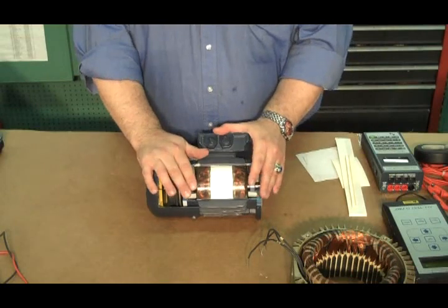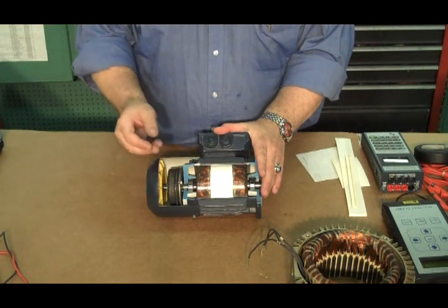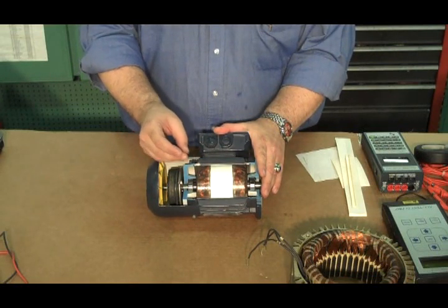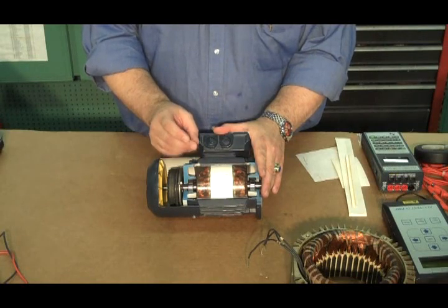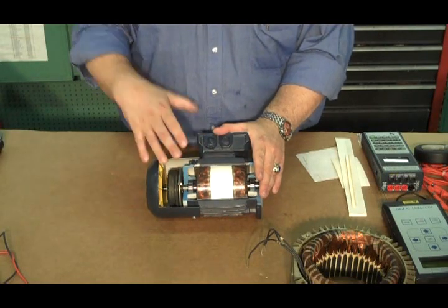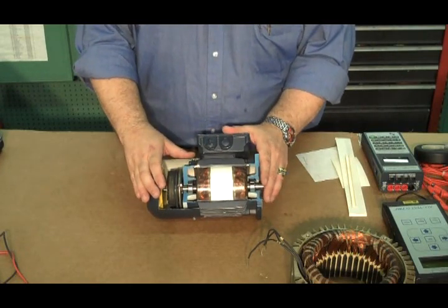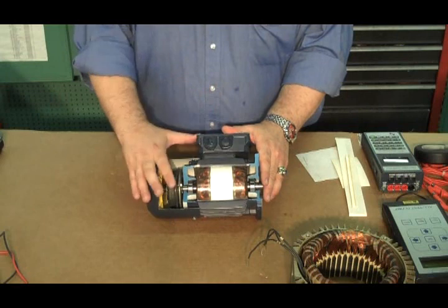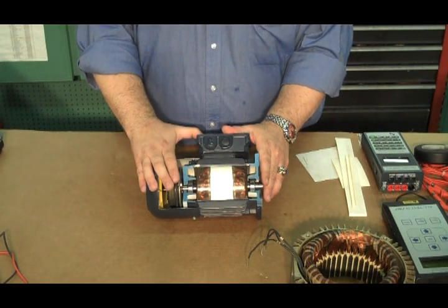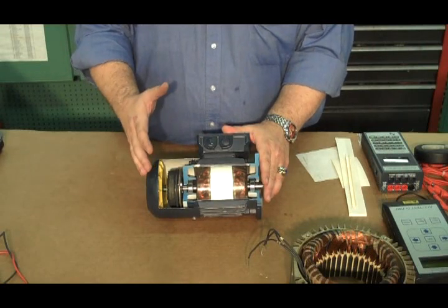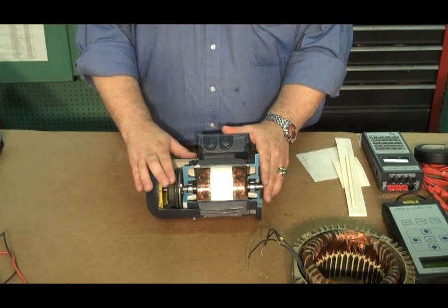Now, windings fail in about 35% of all motor failures, and within that, about 15% of that 35% will actually ever go to ground, including through the motor fault. So when a technician goes to troubleshoot an electric motor, they get very, very lucky if they are able to determine immediately that they have an electric motor problem. The result will often be that they'll swap a motor out, swap a drive out, move other things around, and so on.